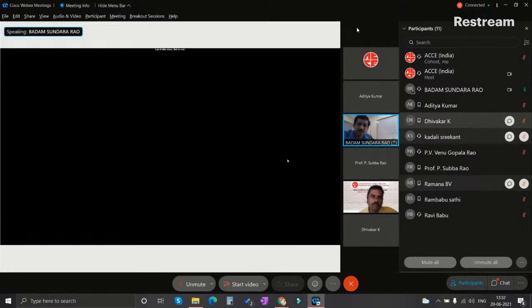We have stratified soil or uniform soil, and at a particular depth the stress is there. For a uniform homogeneous soil deposit, the stress bulb will be significant, that is, the diminishing of the stresses below the bottom of the footing. At the bottom of the footing, you have the stress equal to the contact stress, that is the bearing pressure. That will decrease as you go into depth. That significant depth we generally treat as 1.5B to 2B. Up to 2B, you have 70% distribution. Beyond 2B, you have only 30%.